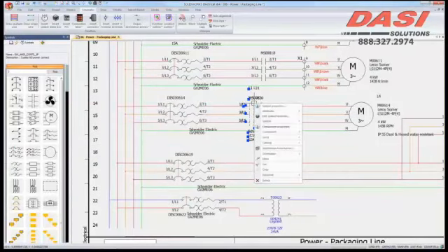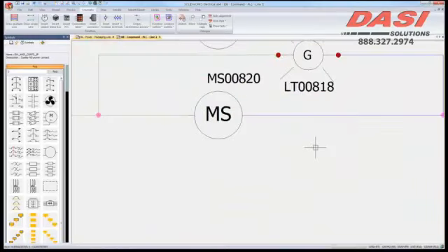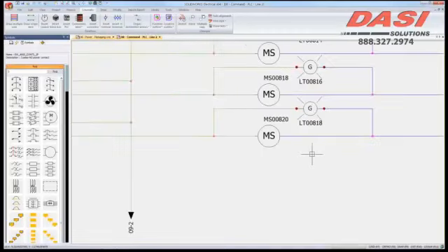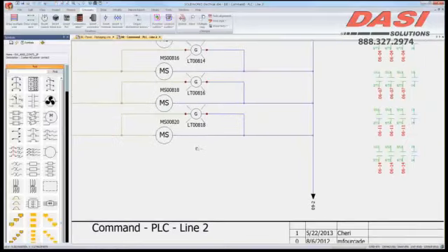I'm going to go ahead here and now go to something called a go-to statement, which is what the SQL database is now allowing us to do. With this, we can actually navigate through the entire project without actually having to open up the sheet. The software is going to simply open up the sheet for us and take us directly to that specific unit. And when it does, what you will find is that not only is it taking care of the coil and associating those contacts, but the contacts themselves, this is the actual cross-reference for that coil that is automatically populated.